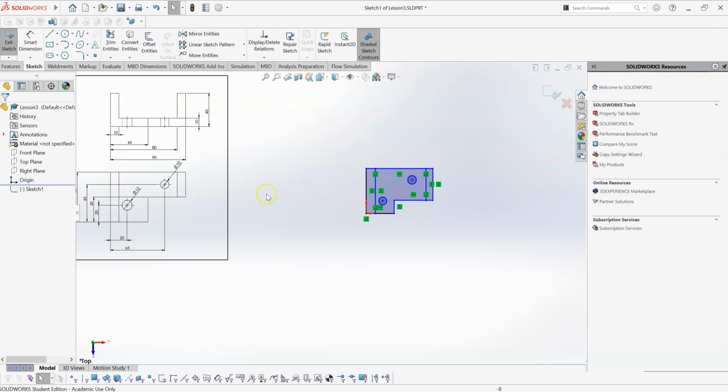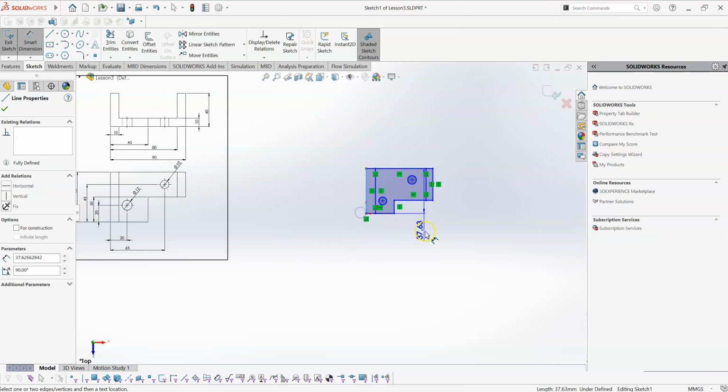Okay, so if I take the overall shape of the outline here, that is 90. It's 90 from here to here, 80 from the left hand side to here, 10 from the left hand side to here, and so on. So you can get those horizontal dimensions from here. So from the left hand side, it is 45 millimeters to here.